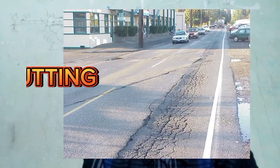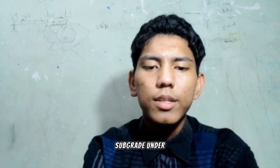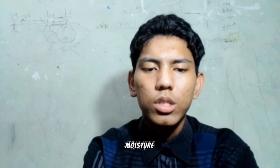And the next picture, rutting. Rutting results from consolidation or lateral movement of any of the pavement layers or the subgrade under traffic. It is caused by insufficient pavement thickness, lack of compaction of the asphalt, stone base or soil, weak asphalt mixes, or moisture infiltration.